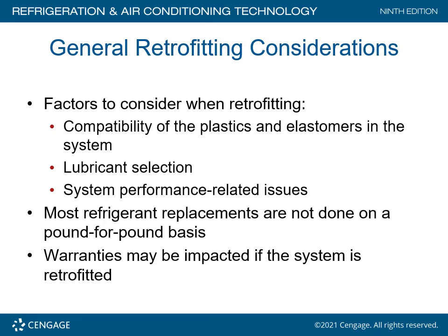There are some exceptions. Let's say that you have an air conditioning system which was installed 10 or 15 years ago, and let's just say that the evaporator coil was rated for 410A. If the metering device is also rated for 410A, as far as the pressure drop through the piston or the TXV valve, then yes, you could put in a new outdoor unit utilizing R410A versus the R22 units, which are no longer available.